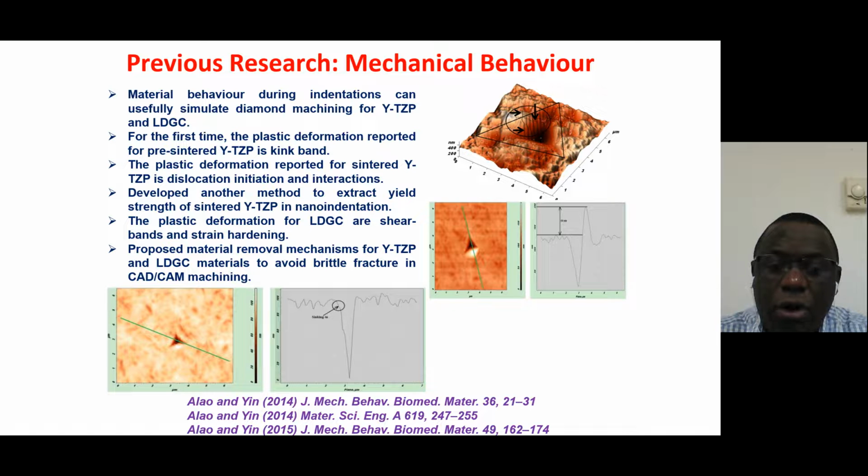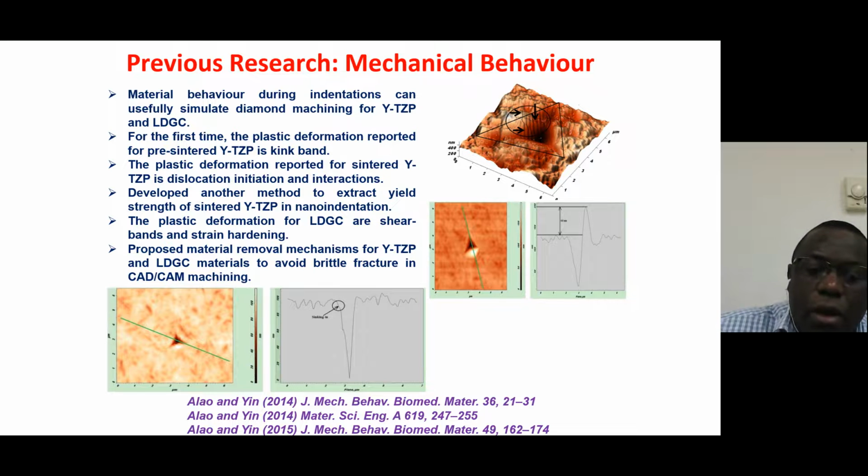Spherical indenter is always made of tungsten carbide, while Berkovich is made of diamond. So if you use spherical indenter, you are going to generate micro stress and strain. That is, you are going to have the stress along the strain, just like the conventional stress strain curve. This is the stress and this is the strain.